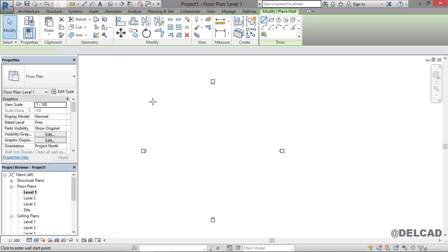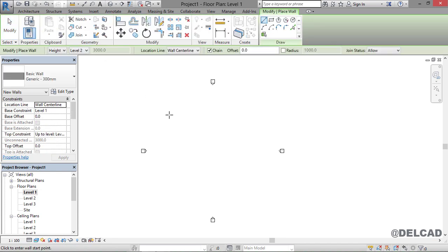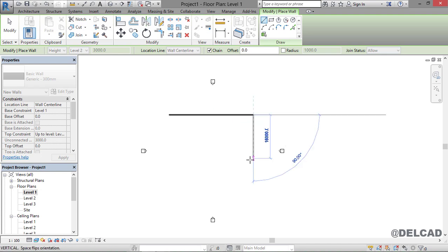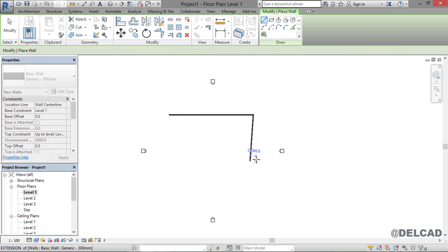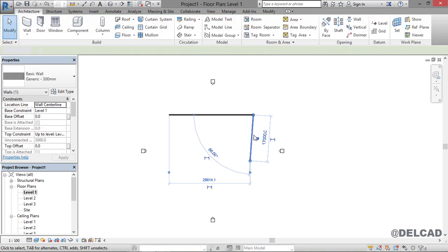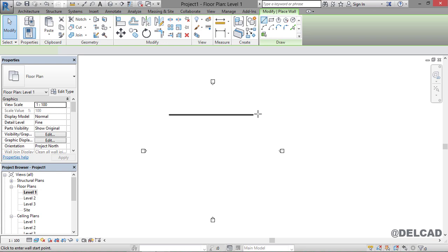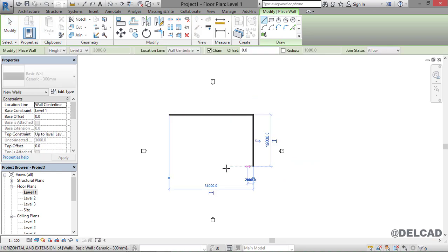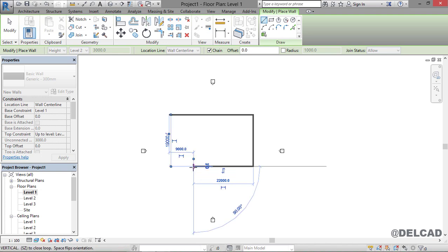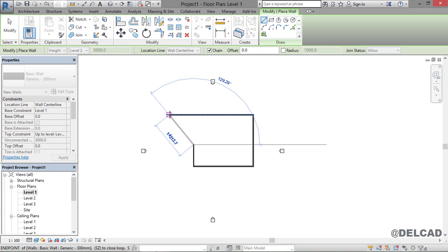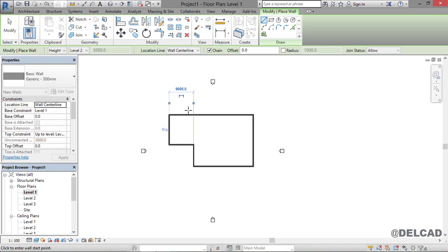Again, let's pick this wall and see how we can create a simple building. We can click and drag to create a building like this. So we can delete this, go ahead, pick the wall tool, and click here to create a building or a wall like this. We can hold the shift key to make sure that our drawing is orthogonal, so we can draw either horizontally or vertically without being inclined. We can make use of the shift key to do that, and then we can use polar tracking or snap settings to track the end of this wall,